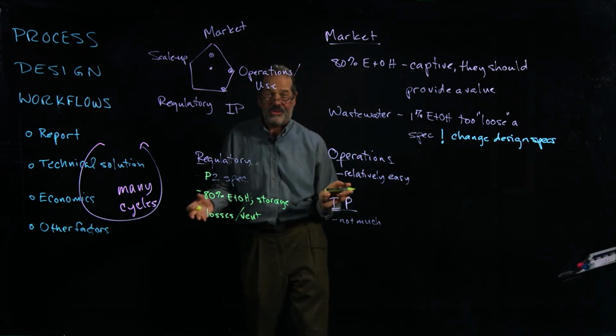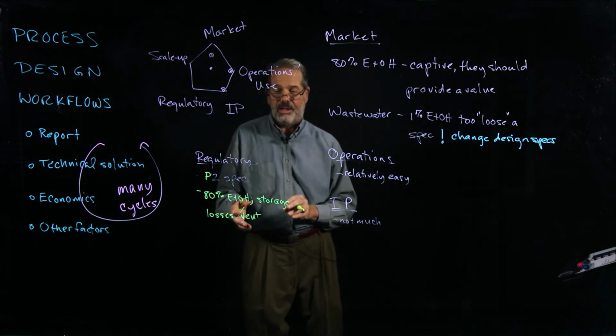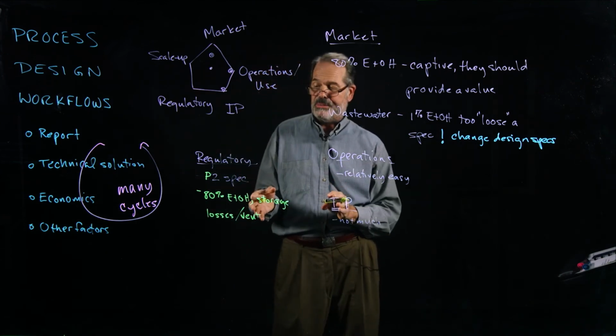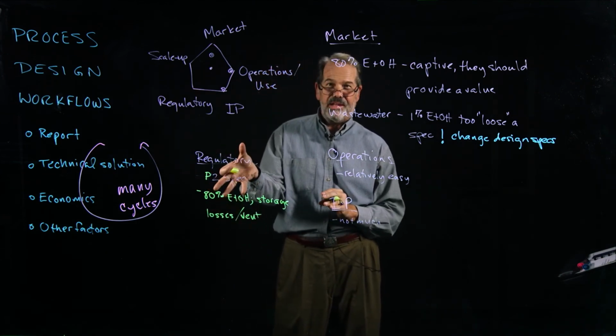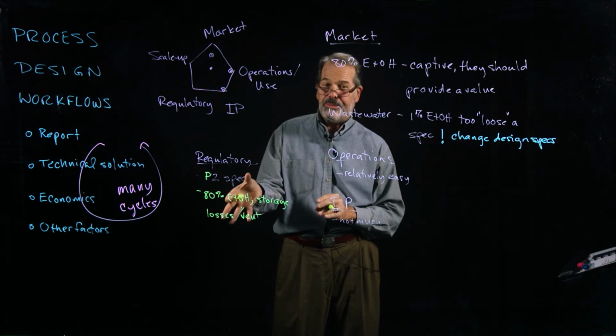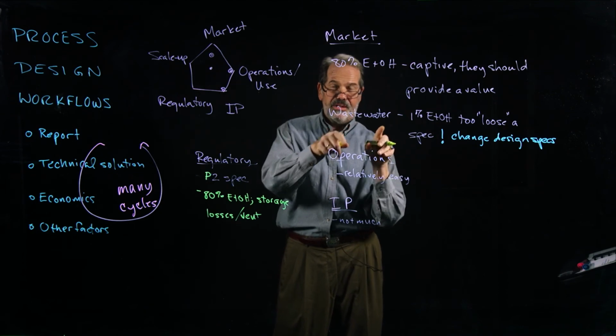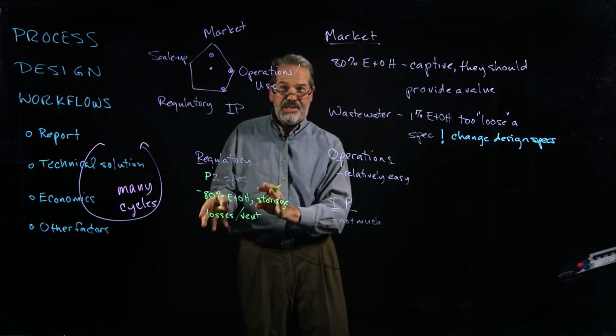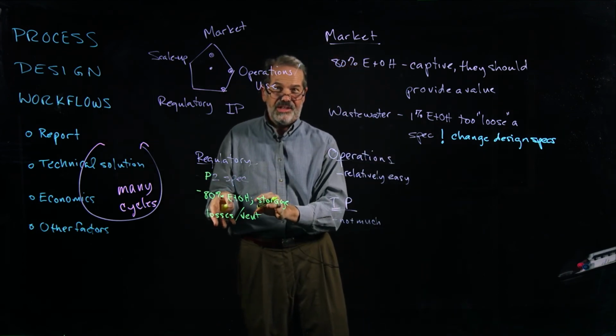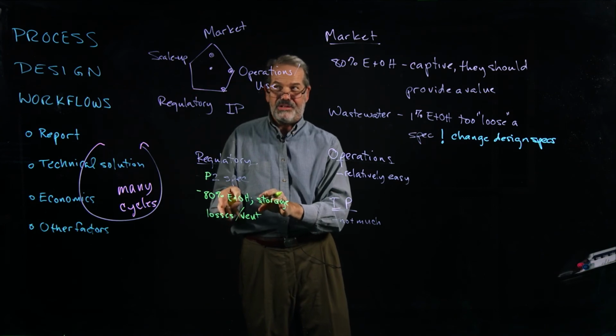If we're going to store it for any period of time, we have to choose a storage temperature and make sure we're not getting too much release to the atmosphere. Same for whatever we're going to do with this wastewater stream. It's going to be stored someplace. Do we need a special vent condenser on that storage to meet specs?